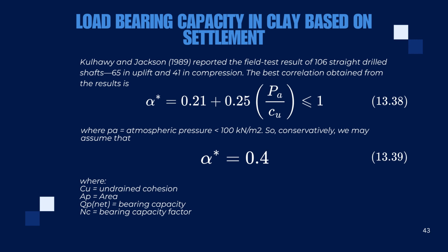Kulhawy and Jackson performed field tests on 106 drilled shafts, 65 in uplift and 41 in compression. From these tests, they derived the best correlation for estimating the adhesion factor alpha. The correlation shows that alpha depends on the ratio of atmospheric pressure PA to cohesion Cu. To be conservative, the value of alpha is typically taken as 0.4. With this value, we can calculate the skin resistance and the point resistance to estimate total load-bearing capacity.